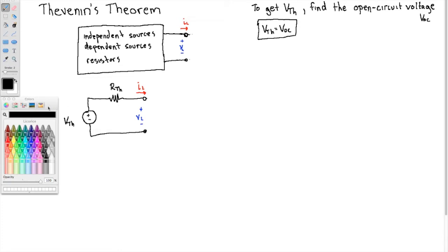All right, well, the next thing we need then in the transformation is the Thevenin resistance. And notice in this circuit, there are actually going to be two cases. So we'll say to find our Thevenin resistance, there are going to be two cases, and the previous video illustrates why there are two cases. But we need to handle dependent sources and independent sources differently, separately, I should say.